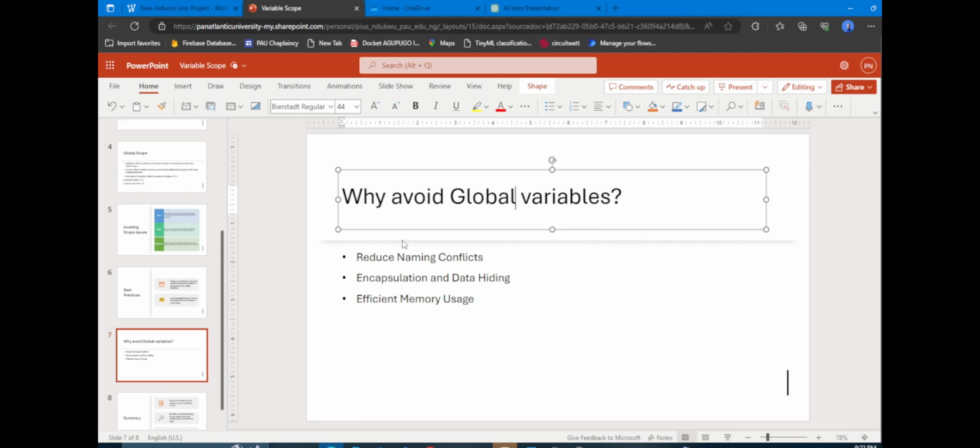That 1 MB is allocated to that global variable throughout the whole lifetime of the code, so the rest of the memory I have is 4 MB. But if it was a local variable and I put it in void setup, when void setup is done running, the 1 MB it took will be released, so I have my 5 MB back. I can now use it to run code. So local variables are better for efficient memory usage.